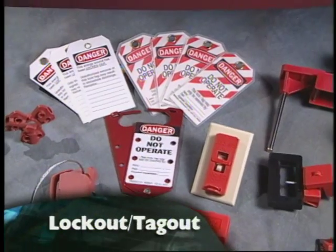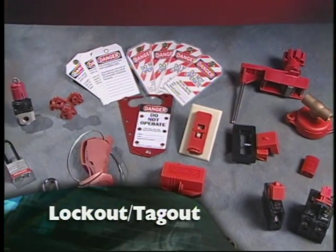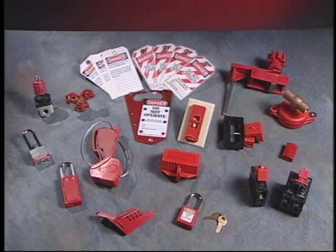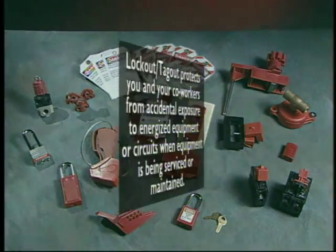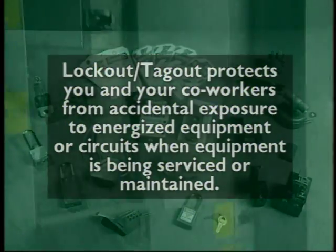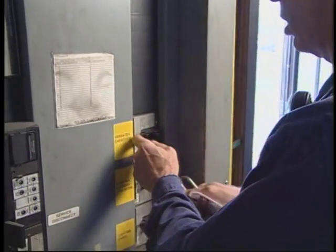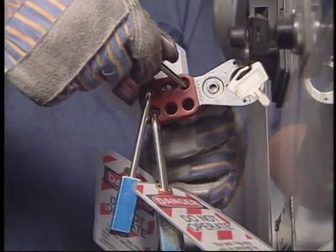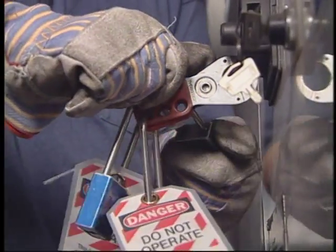Before we wrap things up, let's take a look at a few more important safety issues you need to keep in mind. Lockout tagout is the process of using locks and tags to block the flow of energy from a power source so equipment won't accidentally release energy or start up. This protects you and your coworkers from accidental exposure to energized equipment or circuits when equipment is being serviced or maintained. Lockout tagout affects everyone who comes in contact with energy-powered machinery and equipment, although only certain workers are qualified to apply lockout devices and tags.